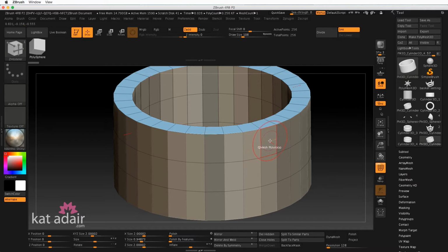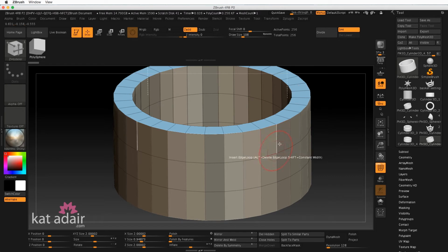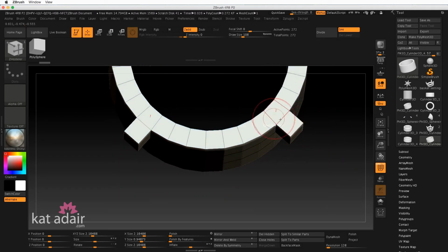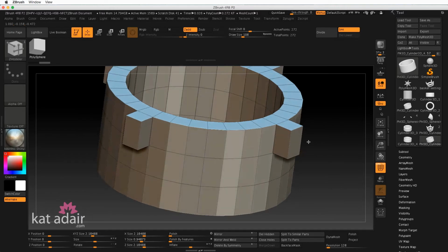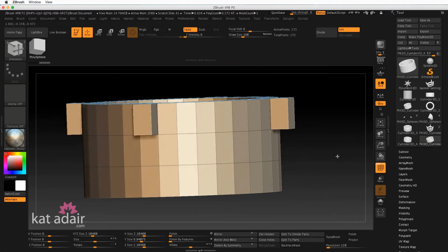Hover over one of the polygons though and press the space bar. I need to make sure that this says Polygon Actions. We've chosen QMesh and a single poly. Once you have all three of those, if you go out and click and drag this little polygon out, you want to make that sort of squarish. So it'll be approximately a square on the top. Not exact. It's skewed a little bit, but that'll work just fine.